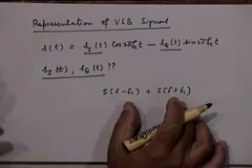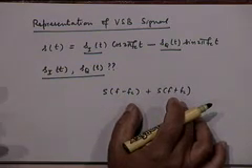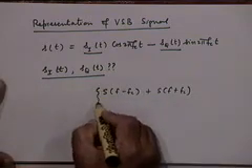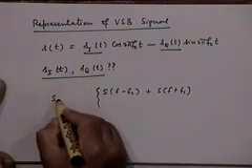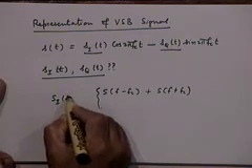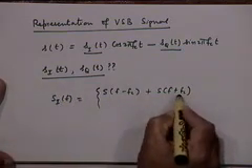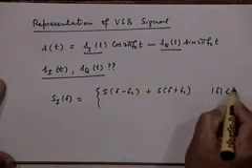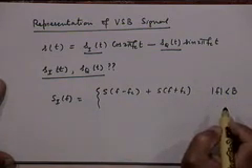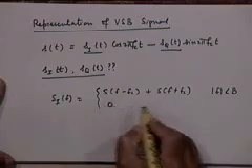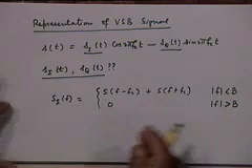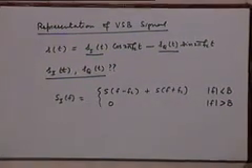Out of that, when you do the low pass filtering, you retain only the component around the baseband. So basically what you are saying is that the signal s_I(t) that you will recover would have a spectrum which equals this for mod of f less than the bandwidth, but equals 0 for mod of f greater than the bandwidth, because you are low pass filtering it, right.